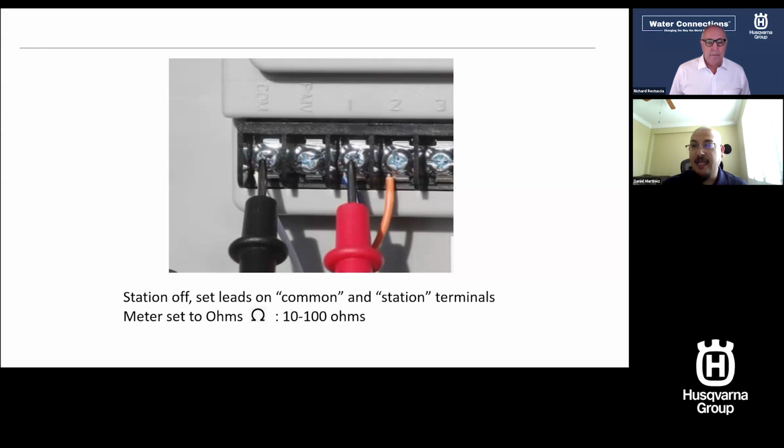If this reads high, then I would go down the line to that station that you're looking at, disconnect from the wires, do a solenoid test, and test if that solenoid is good or bad. If that solenoid is good, then you've got a bigger problem.